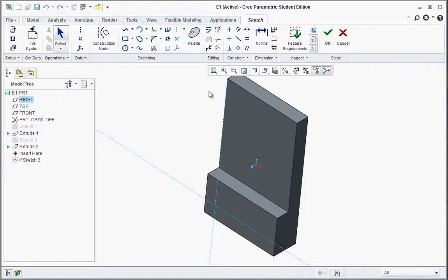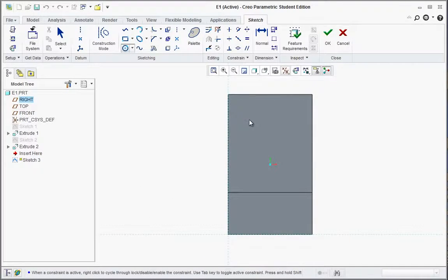So we're sketching on this surface, so you can now take the center point tool, which is a circle tool essentially, glide up to this upper left quadrant. Now if you prefer, again, you could go to the AB button and go to front. This might be helpful. And so the upper left quadrant, click and drag out a circle, and then middle click a couple times. And you'll get the dimensions to appear. Some of these we want, some of them we don't really want. According to the book, we actually want this one right here, and we're going to make that an offset of 1 inch from the left edge.